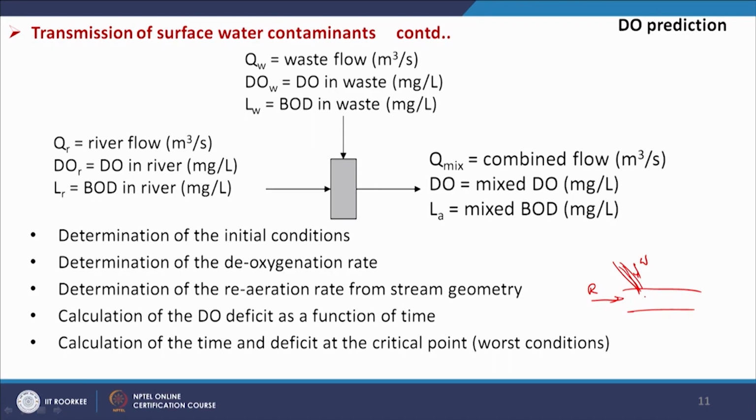After that, immediately it mixes. So, we get our initial concentration after mixing, and here the microbial activity will start and gradually the pollutants will be converted. Different phenomena are going on here: organic compounds are being degraded by the microorganisms, and the concentration will vary, maybe with precipitation etcetera. So, that way we will see how this phenomenon goes on.